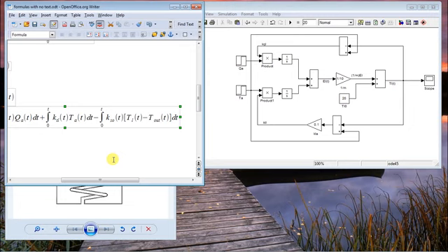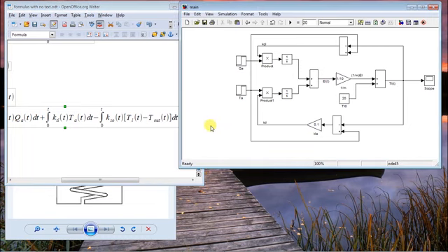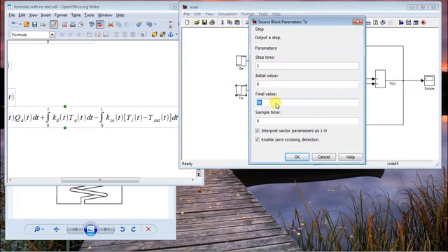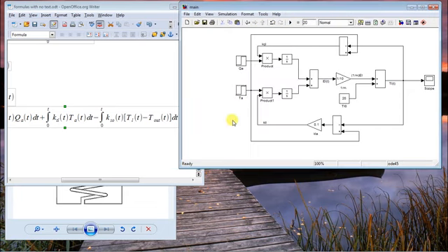And what this changes in our system, now that the environment also influences the liquid temperature inside the tank, is that the liquid temperature will not be able to rise anymore to this step input over here at 50, because it will constantly lose energy at the surface, so it will constantly lose temperature in the entire volume of it.